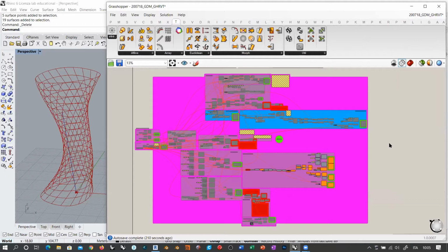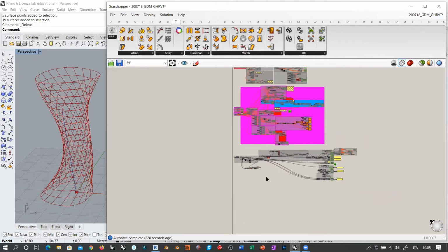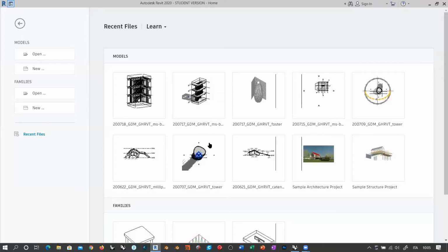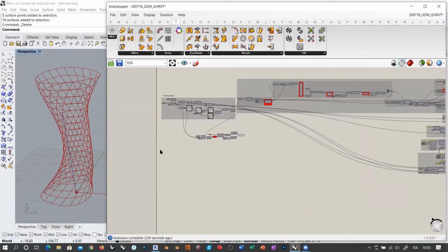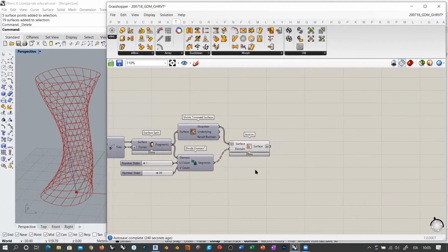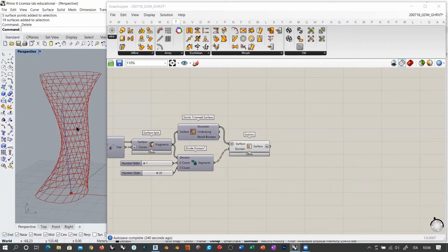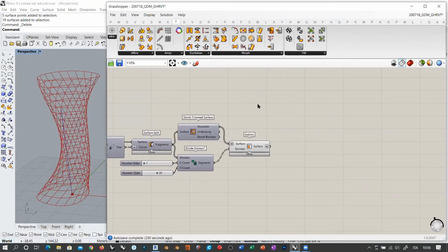This is how Revit sees things. Now, if you try to force Revit to consider, for example, a node between a floor and a wall with a variable inclination, in that case Revit simply cannot solve that intersection. We are going to see this eventually because I'm going to use this surface to define a wall, but this is going to happen later. So there are some things that simply cannot be solved or understood by Revit. So try to keep things as regular as possible.